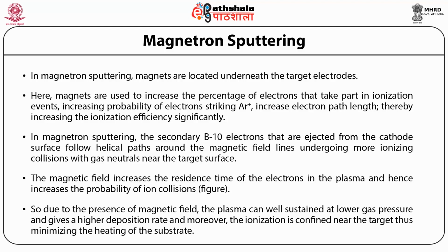So, due to the presence of the magnetic field, the plasma can be well sustained at lower gas pressure and gives a higher deposition rate, and moreover the ionization is confined near the target, thus minimizing the heating of the substrate.